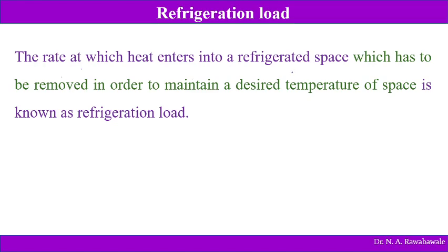Therefore the heat energy which enters into the refrigerator continuously because of the temperature gradient, because of opening of the door, or maybe any other reason, has to be removed continuously, and that is known as the refrigeration load. So it is defined as the rate at which heat enters into the refrigerated space, which has to be removed in order to maintain the desired temperature of the space.